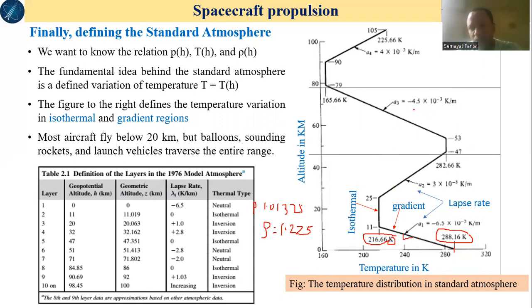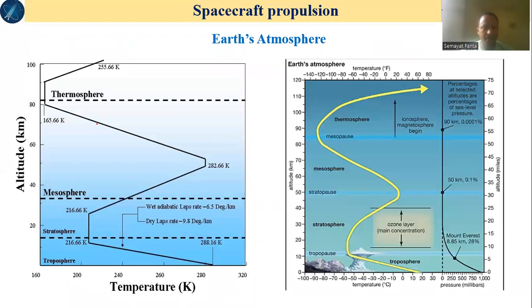There are different lapse rates in different regions, and you will find the temperature distribution and lapse rate distribution for the regions we mentioned. Basically, for quick reference at different layers, when the geopotential altitude is 0, what is the geometric altitude? Next, you may be asked to find geometric altitude from geopotential altitude, and this will help as a reference, with the lapse rate at every different altitude. So this is a summary of what we have discussed today. These are also similar summaries.